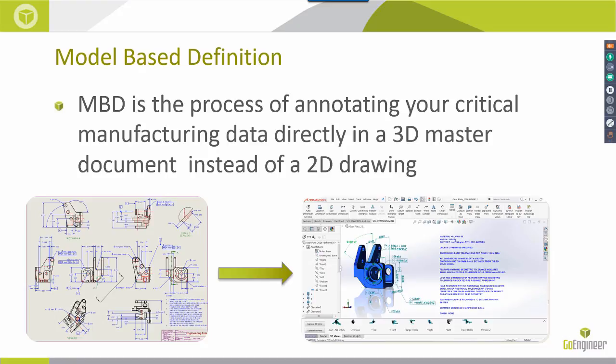What we're trying to get to is conveying our design intent, our PMI, directly with the model. And there are different classifications and levels. Most of our customers are in what they call classification 2, where the drawing may still be the driving document, but the model is supplementary and complementary. What we'd like to do is move to a class 5, wherein all of the information is conveyed via the model, and we don't even need a 2D drawing anymore.